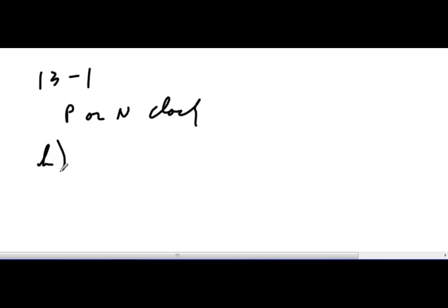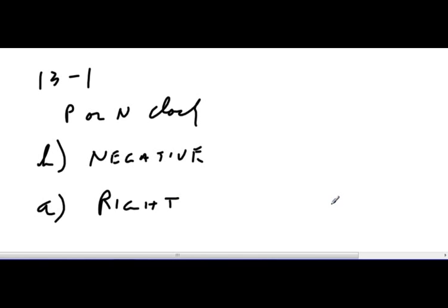So the B part of the answer is negative clock pulse. Okay, the A part of the answer. Am I shifting right or am I shifting left? And when the clock pulse occurs, whatever in Q3 is going to Q2, therefore I am going in the right direction. Okay, by the picture, so I'm going right. Oh, excellent. Next problem.